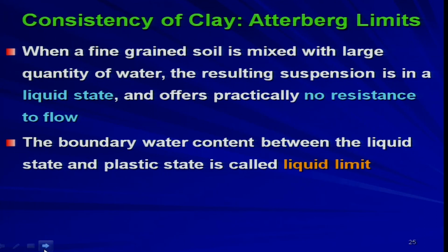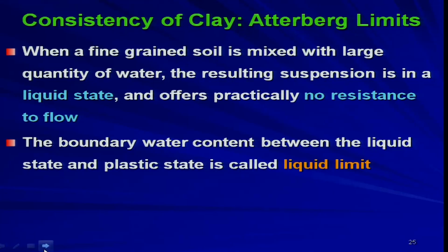So, now we are defining different limits. The boundary water content between the liquid state and plastic state is called the liquid limit. Please try to understand, this is very, very important. Based on these limits, basically you can get the property of the clay soil.